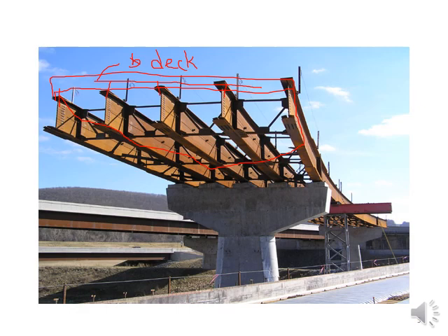These stringers are not like the interior ones having different dimensions and the exterior ones having different dimensions. These stringers are equally placed and equally designed, and they are called plate girders. All are called girders, and that's why it is called a steel girder bridge. So all of the longitudinal members placed to carry the load coming from the bridge deck are called steel girders.